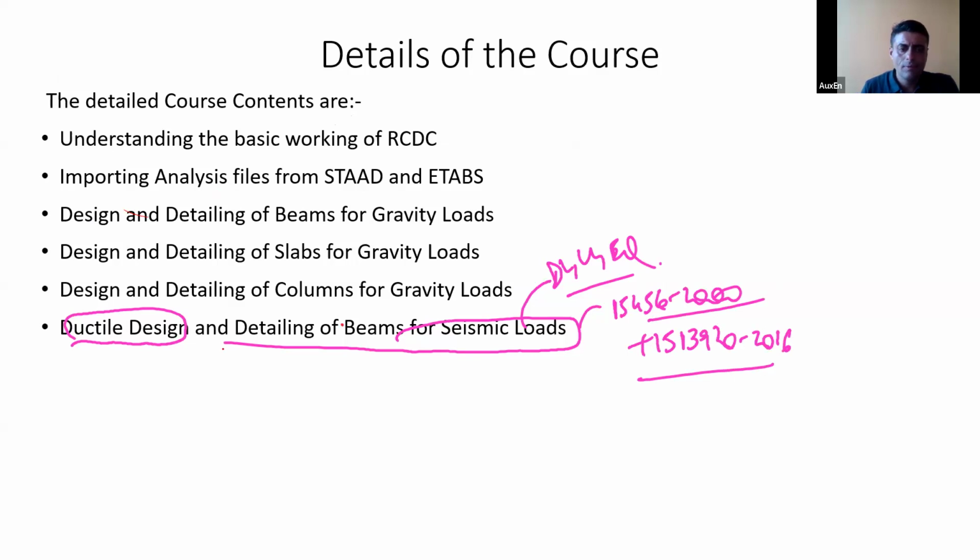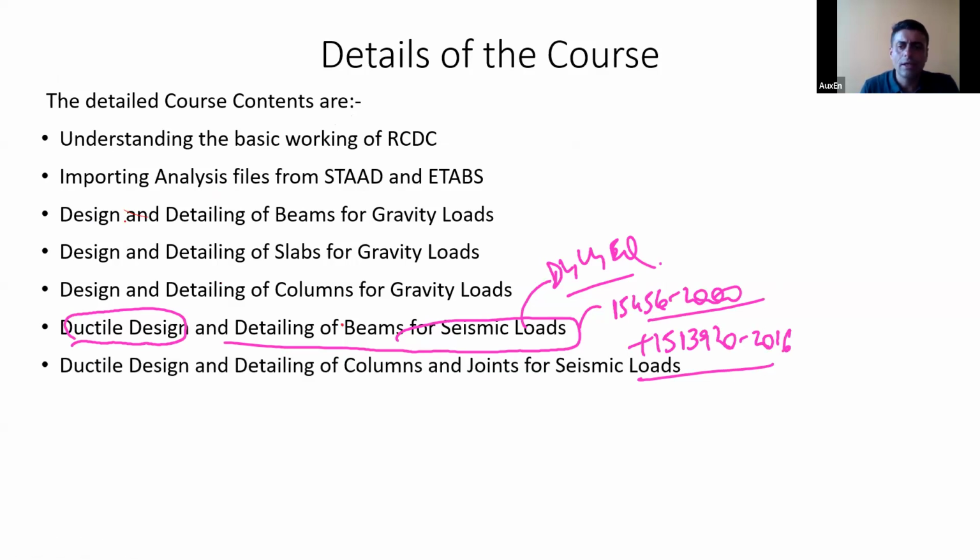After that, we will also do the ductile design and detailing of columns and beam column joints for seismic loads. Again, the provisions of 13920 and 456-2000 will be adopted for the ductile design and detailing of columns and joints.